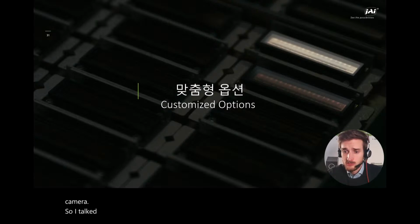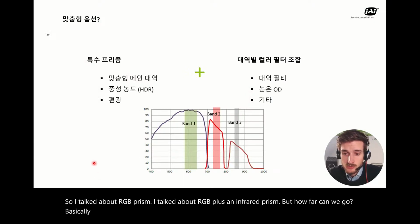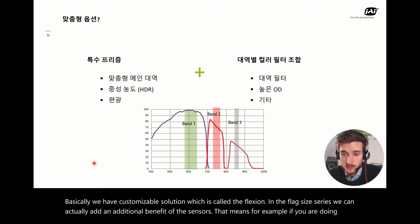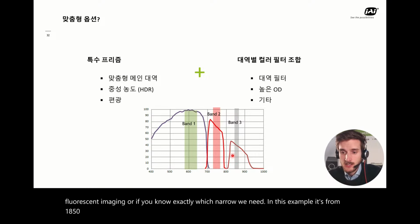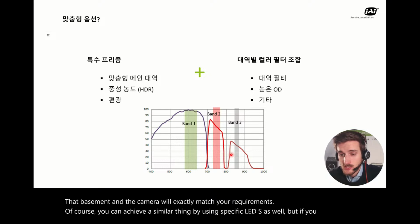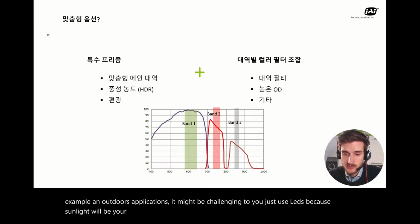So I talked about RGB prism, I talked about RGB plus near-infrared prism, but how far can we go? Basically, we have a customizable solution which is called the FlexEye. In the FlexEye series, we can actually add an additional bandpass filter on each of the sensors. That means, for example, if you are doing fluorescent imaging, or if you know exactly which narrow waveband you need, in this example it's around 850 to 860 nanometers, we can add a bandpass filter on the sensor for that waveband, and the camera will exactly match your requirements. Of course, you can achieve a similar thing by using specific LEDs as well, but if you have, for example, an outdoors application, it might be challenging to just use LEDs because sunlight will be your main source of illumination.